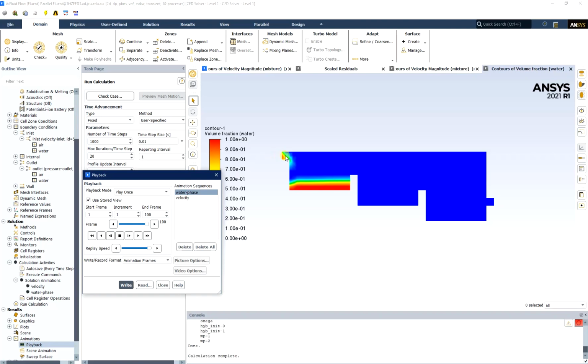If you have it about 0.2, you will double the filling process, or if you have 0.5, you will make it 5 times faster. However, when it is too fast, for example, 1 or 2 meters per second, the flow may go over the step and not fully fill the water over here because it works like a Z, going from the inlet directly to the outlet.